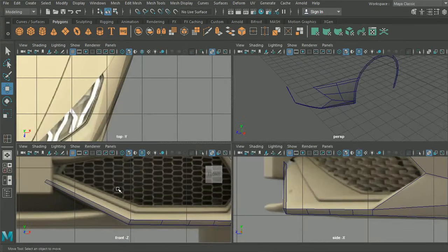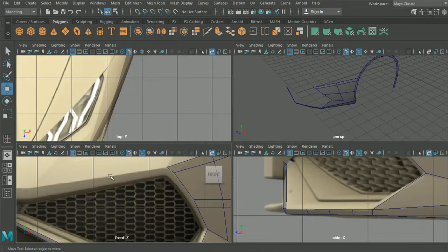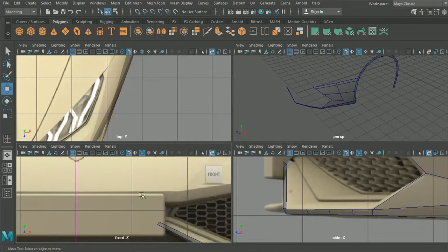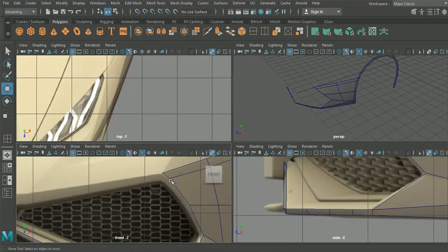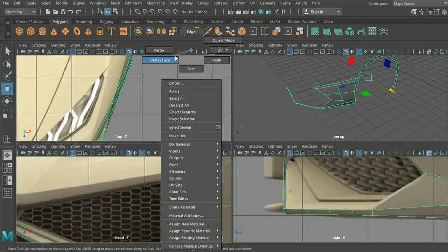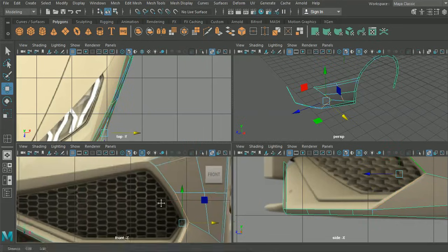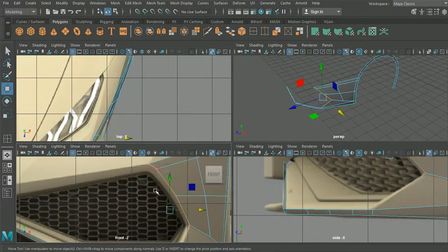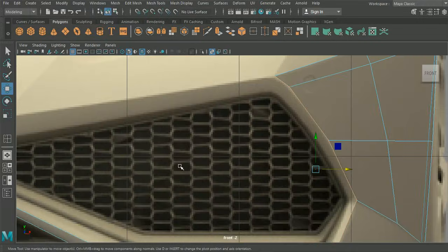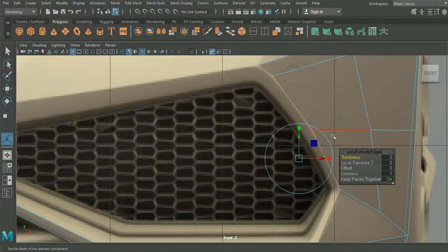The next section here, we can see that we actually need to create a forward facing edge, which is going to align the top section of this bumper here. So we're going to use the exact same techniques as before. We're going to right click here, we're going to select that edge, and what we're going to do is we will bring in the edges of our sideways sections, and then we can do the bottom. So select all these edges here. We can Control E again, and this time we're going to move in.